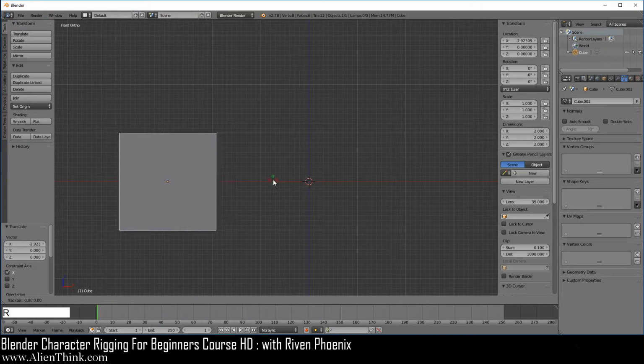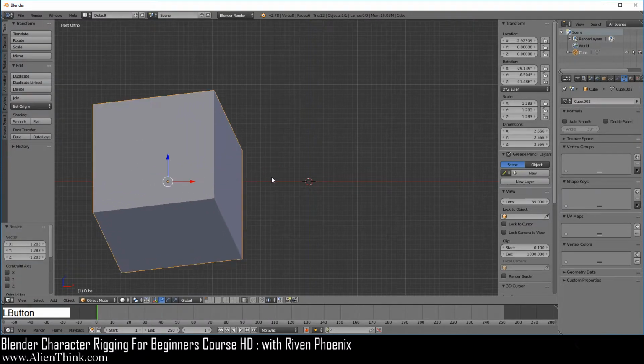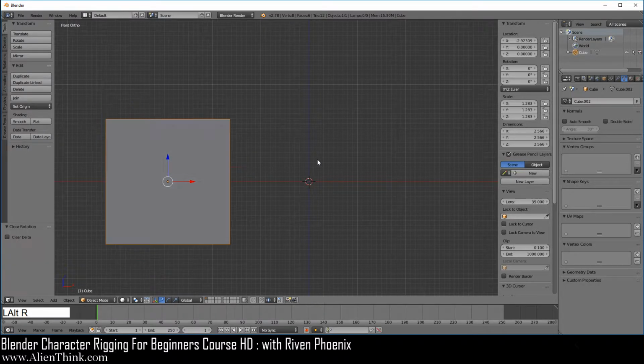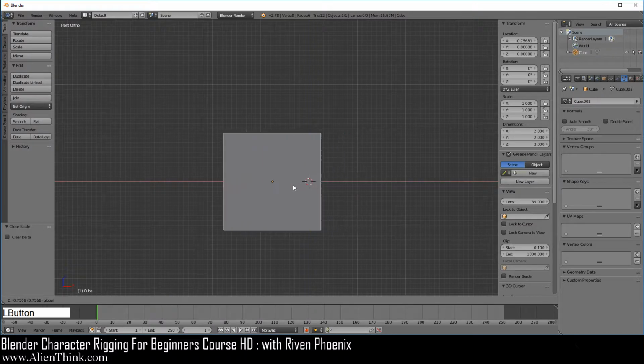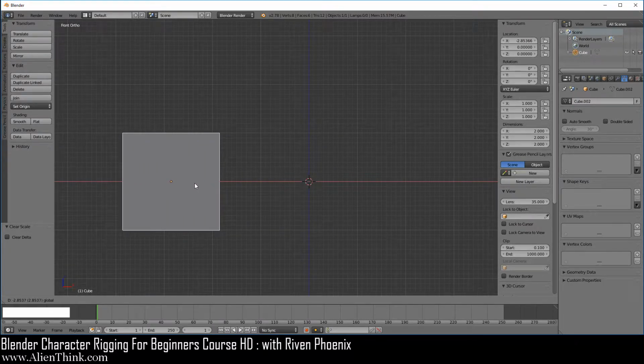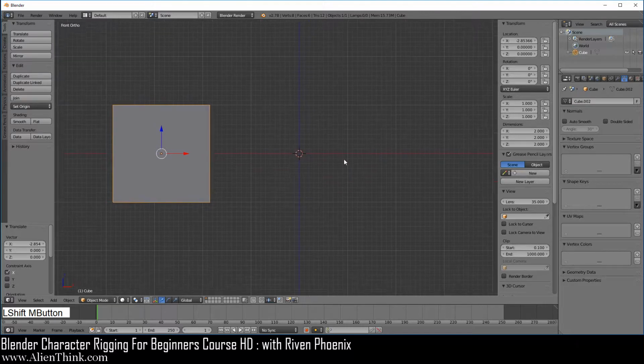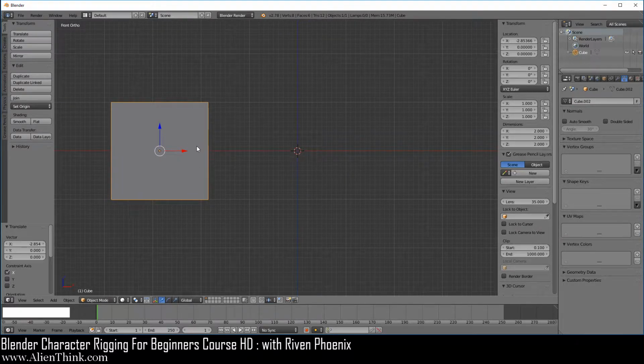Now if you press the R key 2 times, press the S key to scale, since Blender knows exactly what you did to your object, you can reset everything back by selecting Alt-R, G, S, meaning that we are resetting the rotation, location, and the scale. Okay, now go ahead and move this object over here. So now you know how this concept is working in the 3D view when you're dealing with objects.